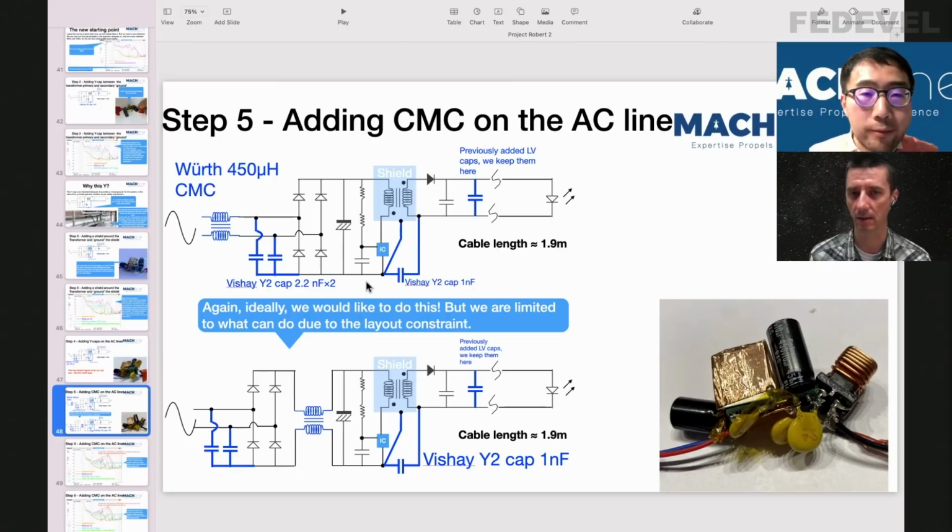Block or cancel? So you block. The canceling is canceling differential noise. So the differential signal is cancelled, but for common mode, it's like a door, basically. I'm blocking you, basically. It's high impedance or what? It's a high impedance for common mode current. Yes.